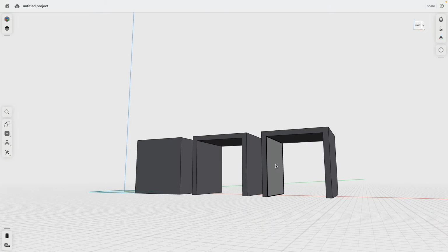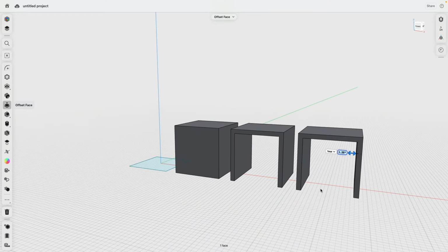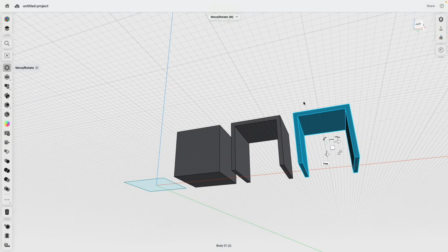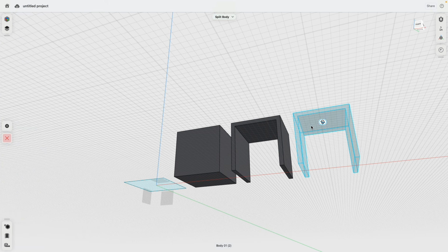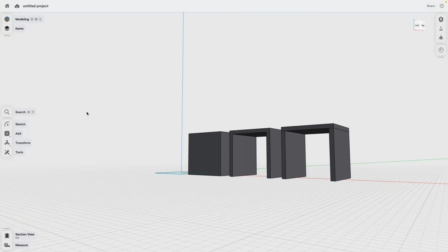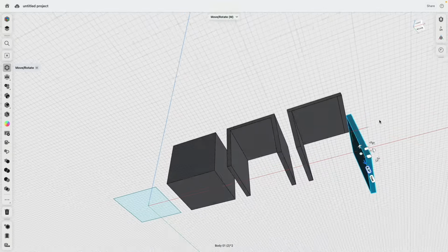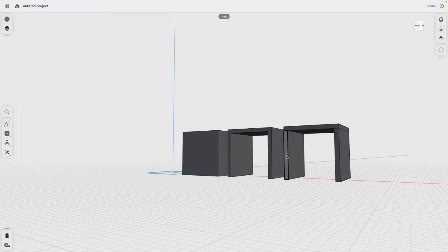And now I will show you how we can separate actually these sidewalls from the top. Select the whole piece. Then go to more, split body, and we select the under surface where we sit. There. Click done. And you see now that this actually disconnected the whole piece. That's pretty awesome. That's like we built one piece and we took a knife and just cut it apart.